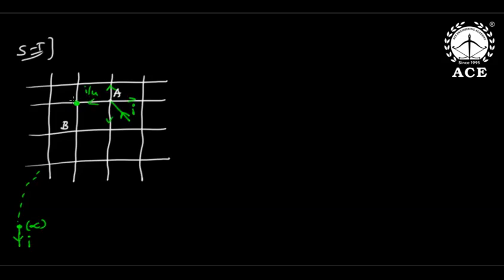Now from this node to infinity, again the path resistance in all paths is equal. So this I by 4 further divides into 3 equal parts. What are the 3 equal parts of I by 4? I by 4 by 3: I by 12, I by 12, I by 12. Okay? So now I still want to do Ohm's law.